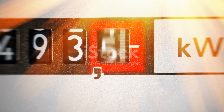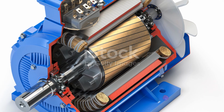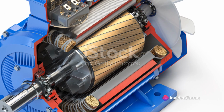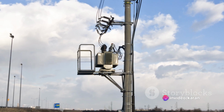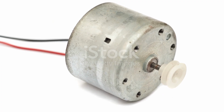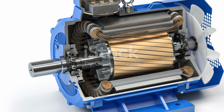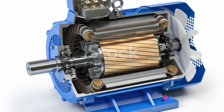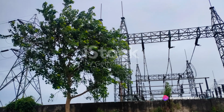a combination of real power and something called reactive power. You see, in any electrical system, the power that's doing the actual work, like lighting up a bulb or running a machine, that's real power. But then, there's also power that's used to maintain magnetic fields in inductive loads. This is what we call reactive power. The apparent power is the combination of these two, real and reactive power.